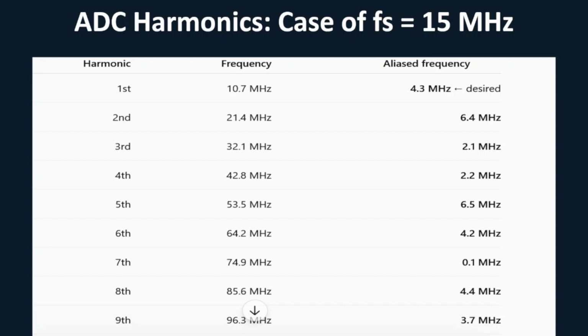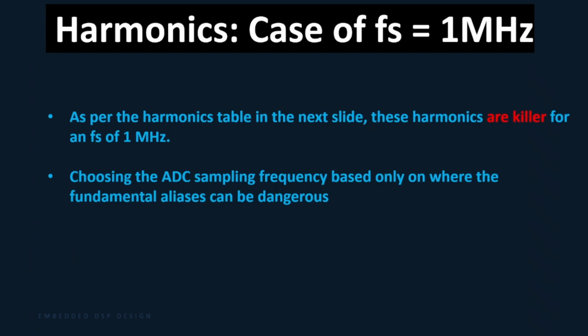And the second thing you'd have to worry about is the ADC or the mixer's harmonics. So harmonics, as I said, I've seen it in the industry, it's a problem. Sometimes you find out about them later in the design process, and it would be very costly to go back and fix them. And it all comes down to the selection of, I would not say the correct FS, I would say a suitable FS, sampling frequency. So you can see how the trade-offs here interact with each other. It's not just one variable, which is the FS, there is more than that.